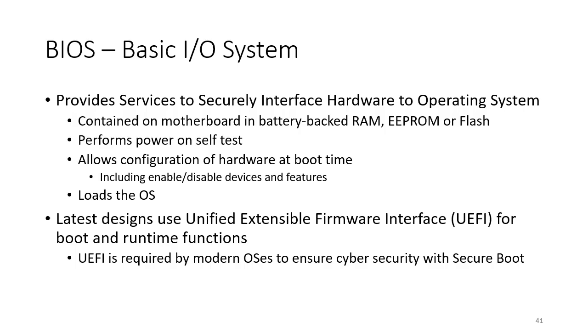Now, the BIOS itself, normally it's contained on the motherboard. So that would either be in battery-backed RAM. So you would have a battery, typically a coin cell battery, that lasts anywhere from 5 to 10 years. If that battery goes flat, then of course, if you power cycle the motherboard, you would lose the BIOS. So normally what the BIOS would do is there would be some sensible defaults which would at least allow it to boot. More likely in modern systems, previously it might have been in electrically erasable programmable read-only memory, or EEPROM. More likely these days it's in flash memory, so it will survive across a power fail, and that minimizes the requirement for batteries.